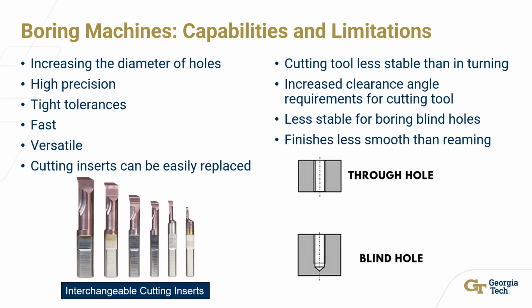Boring is great for increasing the diameter of a hole with high precision and tight tolerances. It is also a very fast and versatile process. The same boring tool can be used for different size holes, and the cutting inserts can be easily replaced.